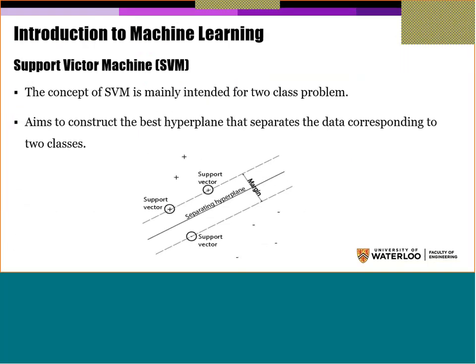Support vector machine works in a different way. For example, if I have the partial discharge and the corona, a two-class problem. Basically, what it does, it puts them like this in a plane and separates them by a hyperplane. Okay, so this is the data, for example, in partial discharge, and this is the data used for corona. So the data will be segregated, and we'll try to maximize the distance between the two classes. Okay, so we use the last points in this class, and I draw a line here, and the last point from this class, and I draw another line. So this is the margin.